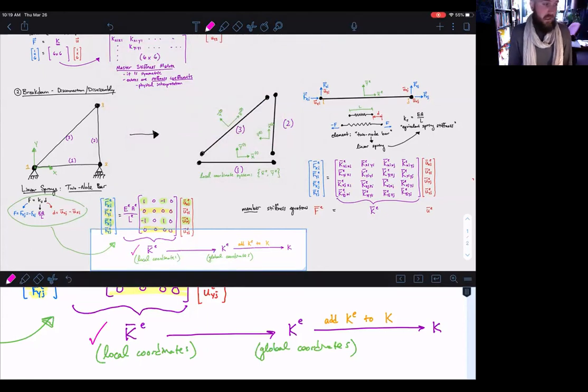Questions? I have a question, but I don't know if it's a smart question or not. The thing is, I was questioning myself, what is the logic behind setting all the parameters in the matrix to 0 and not the forces and displacements? I mean, why shouldn't we say that the displacement in the y direction and the forces in the y direction are 0? Instead, we're setting the parameters inside the matrix to 0.